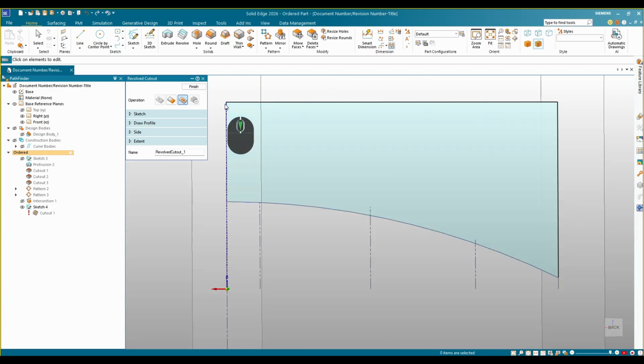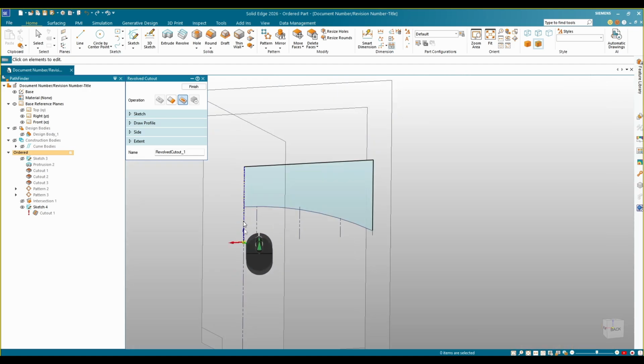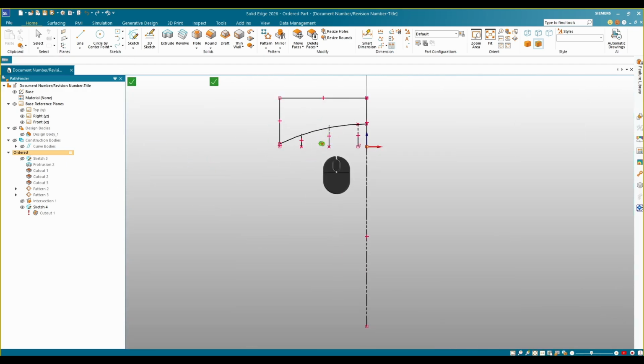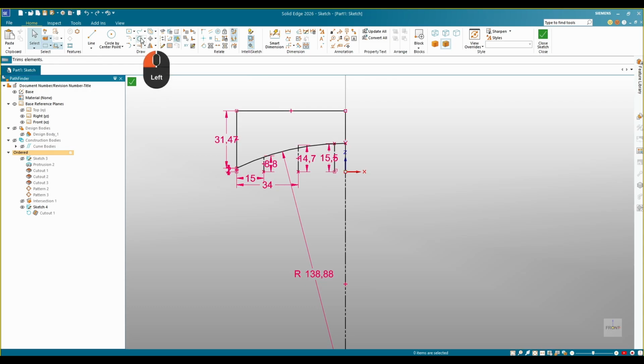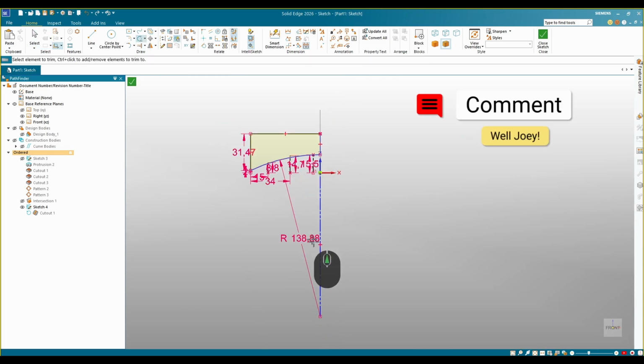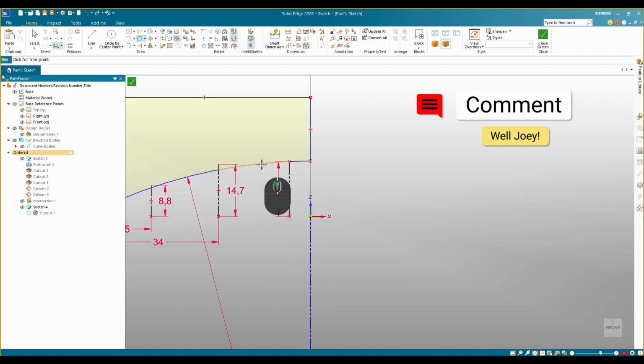And the problem Solid Edge is having here is we have this closed area, but we also have this line here which is going outside our closed area, which Solid Edge can't really make sense of. So I'm going to go to draw profile. So we're back into our sketch, and I'm just going to go to trim, just trim this line here. Now that's made another problem for us, because now we no longer have that line fully constrained and we no longer have our circle fully constrained.